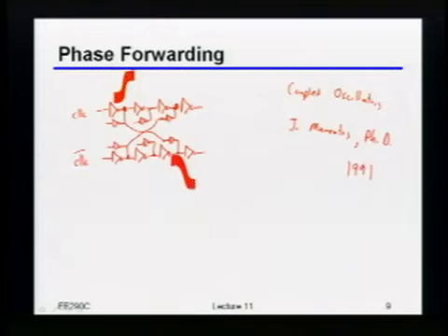So the question was, how does it compare to using an inverter versus using a resistor? Basically, it's the same thing. The resistor just changes whether or not you've inverted to begin with. But conceptually, you have to size that resistor so that you guarantee that you're in the mode that you want to oscillate. And then depending on the relative strength of that resistor or inverter compared to the main path, that will set how much you've sped up the overall operation of the ring.